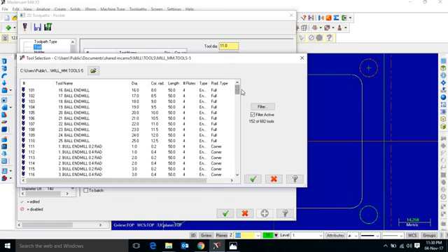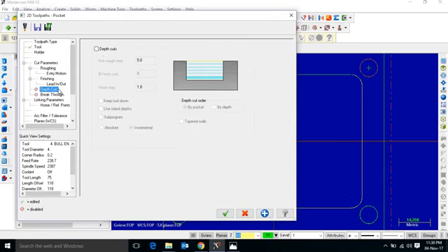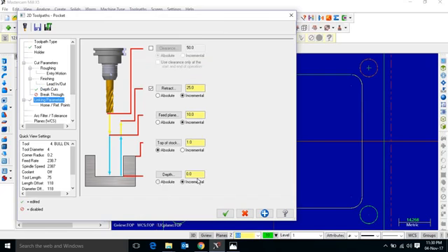So select a tool having a radius of 5 mm or below that. Here we are selecting the 4 mm diameter tool, end mill 4 mm. Okay, depth of cut: 1 mm depth of cut we are selecting. So there are 5 total runs. Linking parameter, depth minus 5.